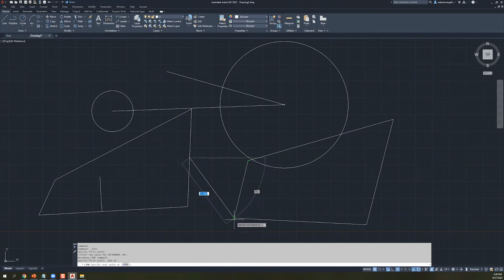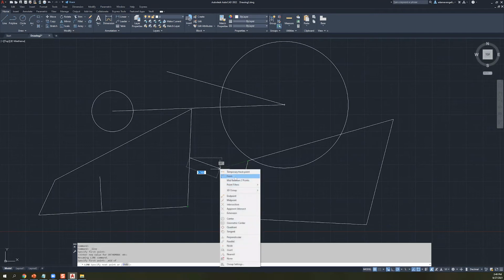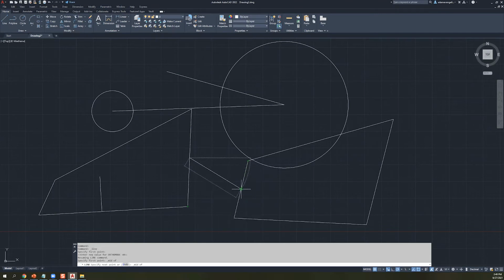And what's nice is that once you place that selection and do something for that first click, you're back to your regular default snaps, right? So now I could go to endpoint, now I could go to tangent or perpendicular, I could do everything else that I want to, but midpoint notably not selected there. But you could do the same thing where you right click and then click midpoint again, and you could snap to another midpoint. This is something pretty valuable to be aware of, right?